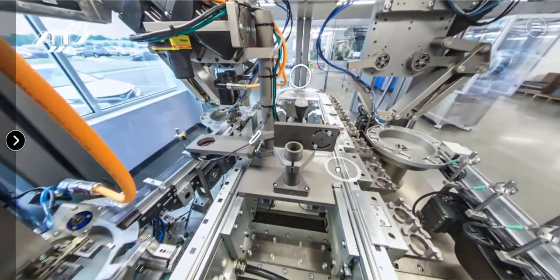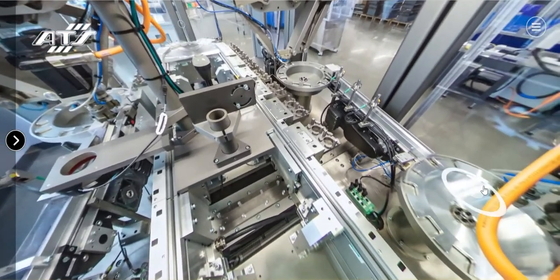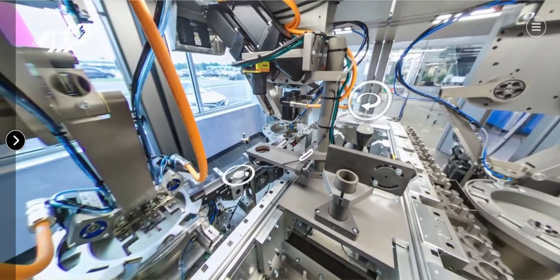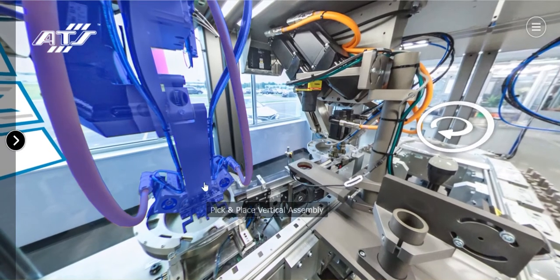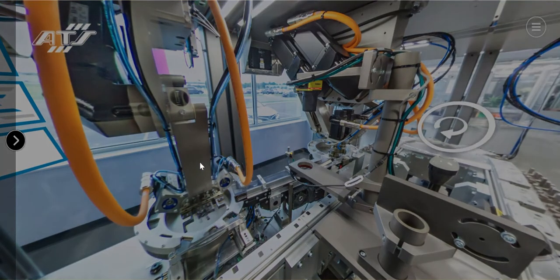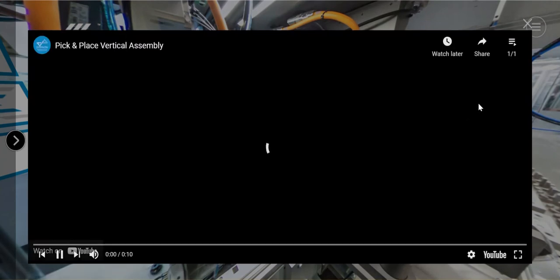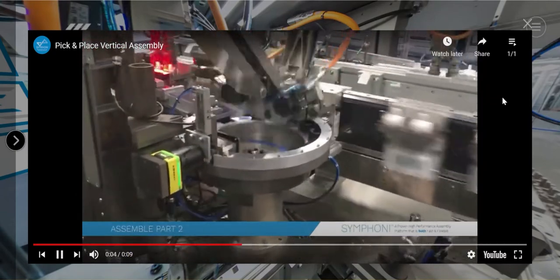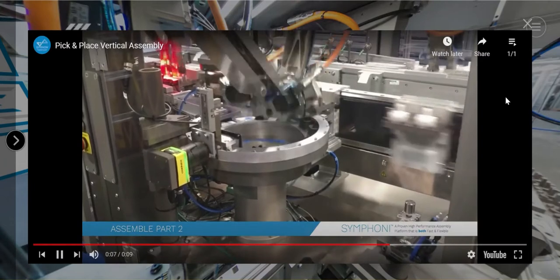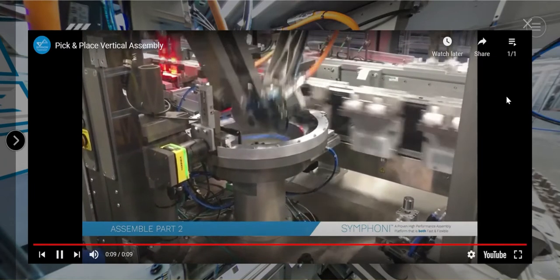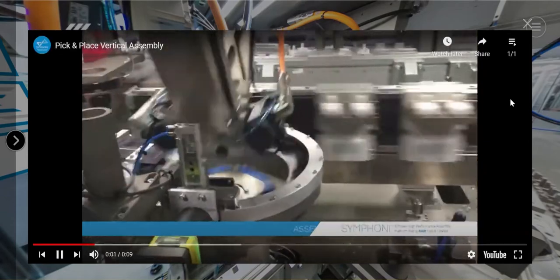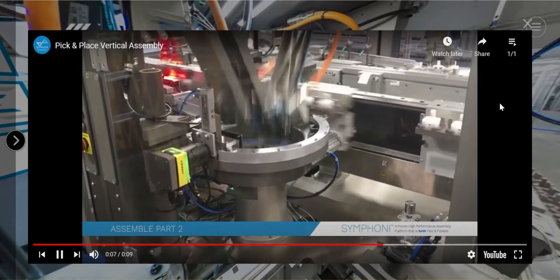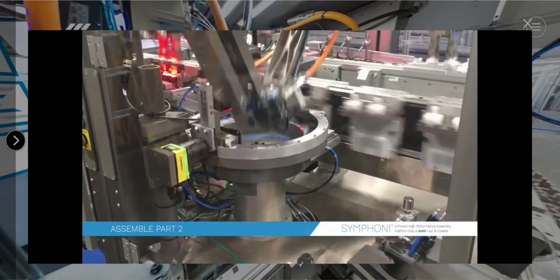So we're at this station here, and we saw that part being loaded. The next operation in the demo system takes place over here on the other side of the system. So we've loaded the white part that you noticed in the video. The second operation then is to place this black part that goes on top of it. So again, 2-up load, again the backside of the line, same sort of thing as we saw before, pick and place stroking between the RSM disk and the pallet. The pallet spends next to no time at all in the station, allowing a very rapid throughput.